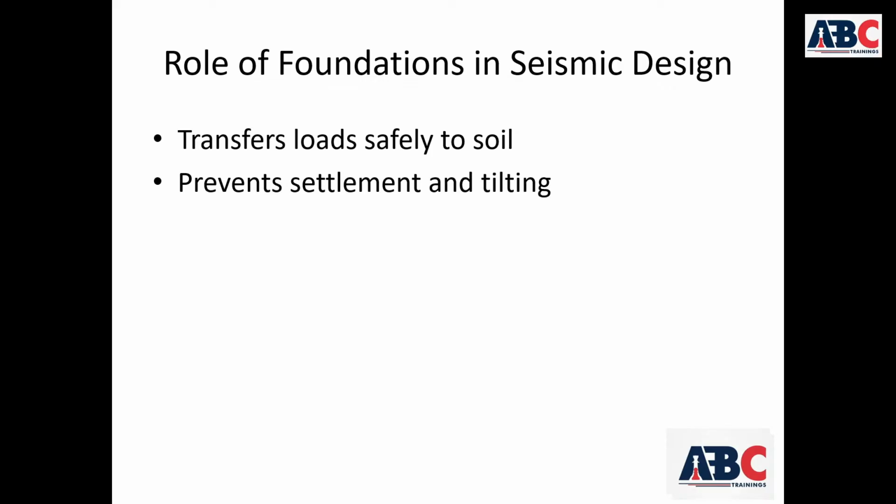One of the major concerns in seismic design is uneven settlement. During an earthquake, soil may lose strength, groundwater shaking may cause compaction, and soft soil may behave unpredictably. This can lead to one side sinking more than the other.